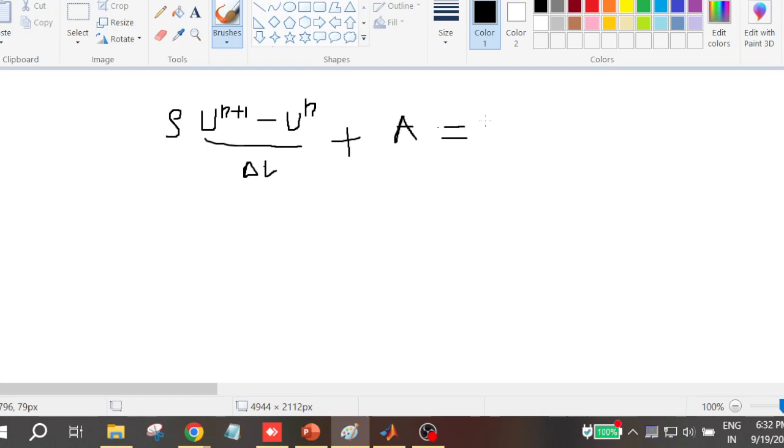you have a pressure term, so let me write it as the gradient of p. This is again in the x direction only. Just take it as it is, plus diffusion. Now what I do is I'll substitute u star instead of u n plus 1, and I will not include this pressure gradient term. I will completely ignore this pressure gradient. Without this, let me just calculate u star. So you will get u star in that way.